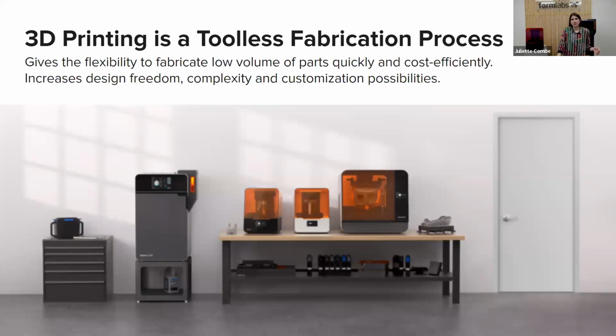So why? Because 3D printing is a toolless fabrication process. So it gives flexibility to fabricate low volumes of parts, and speed. You can produce that very quickly and cost efficiently as well. And on the other hand, you can increase design freedom, complexity, and customization. So you can produce custom parts, custom prototypes, and you can produce custom tools as well. We'll dive a bit deeper into what the possibilities are, but I just wanted to set this ahead. This is really the main reason why we see benefit in using 3D printing.